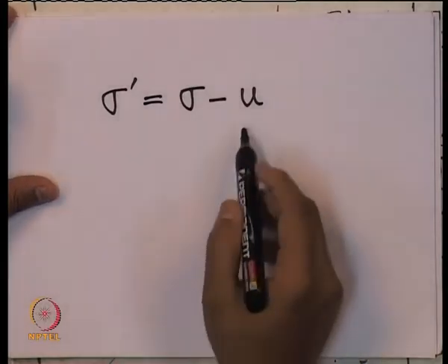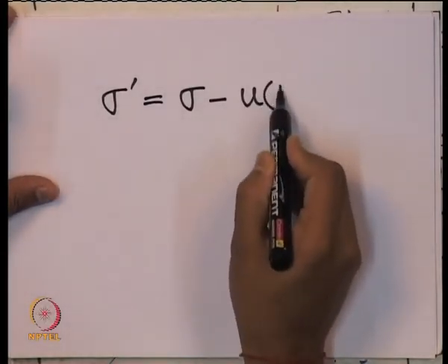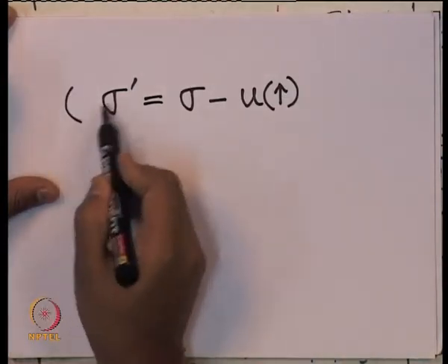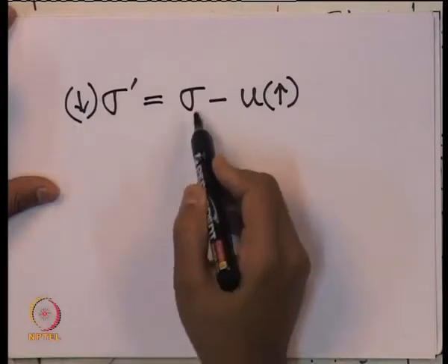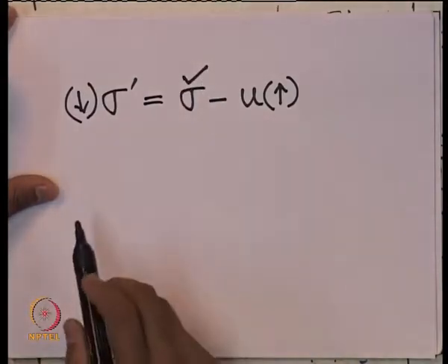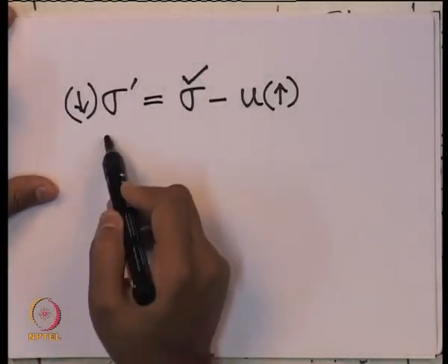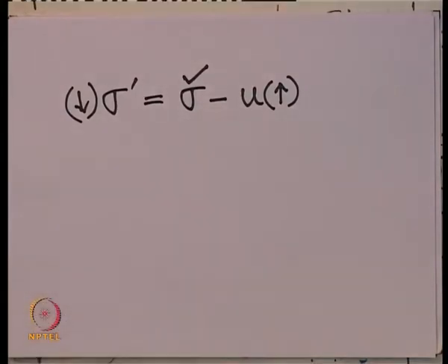So, if this value of u increases during the earthquake process, what will happen? This sigma dash will decrease when sigma, that is total stress, remains constant. Once the effective stress of the soil reduces, it can be considered as liquefaction, either partial or full, depending on various criteria, which we will discuss later when we discuss dynamic soil properties and the liquefaction chapter in this course.